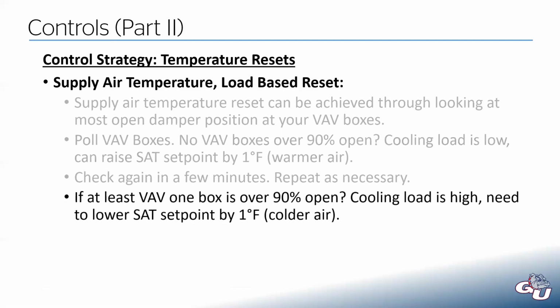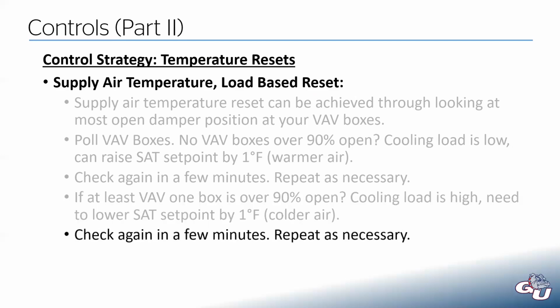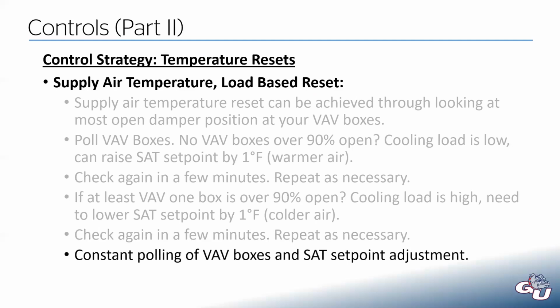And then going the other way, we have a box that is full open. It's saying I need as much cooling as I can get. So let's lower our supply air set point. Just check again, just constant back and forth.